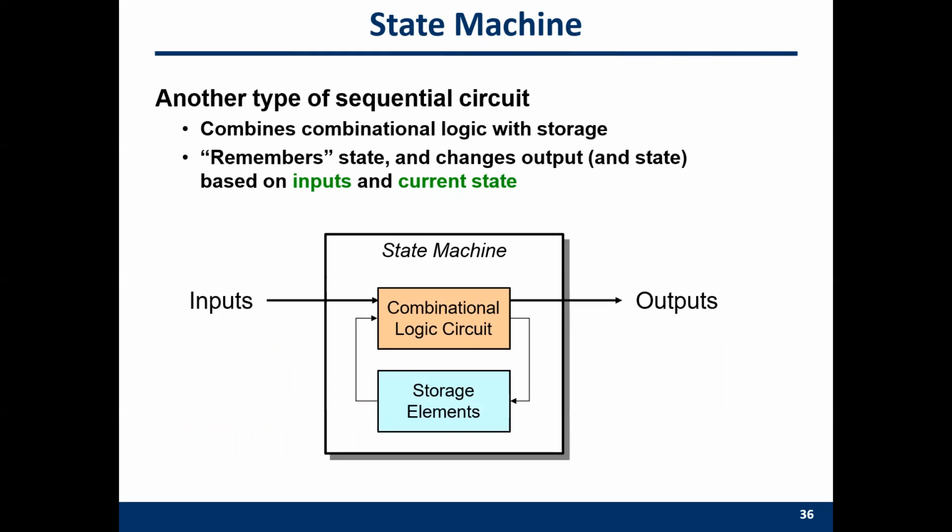The last piece of the controller is actually the state machine. You need to design a controller to control your combinational logic to read the data from a memory element and then do computation for this cycle. And at the end of this cycle, you write back the intermediate result and then read again in the next cycle, do the computation and then write back the results.